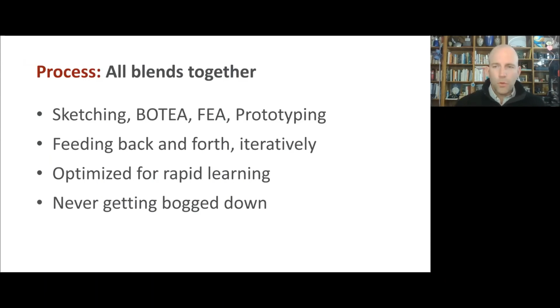So you're really blending all these things together to try to really understand your part while you make it better. So you can see we're using some sketching, some back of the envelope analysis, finite element analysis, and prototyping. And it's really important not to just do this sequentially, not to think, I'm going to sketch, I'm going to analyze it by hand, I'm going to analyze it in CAD, then I'm going to make it, and then I'm going to be done. It does not work that way.